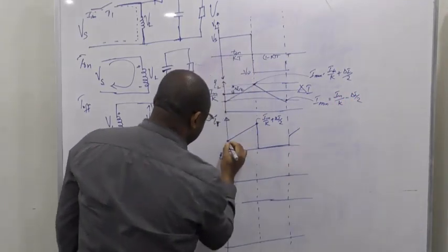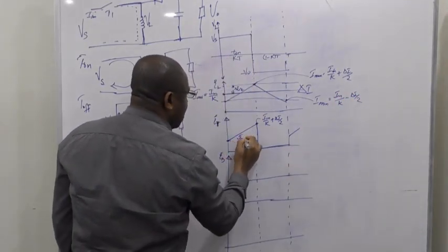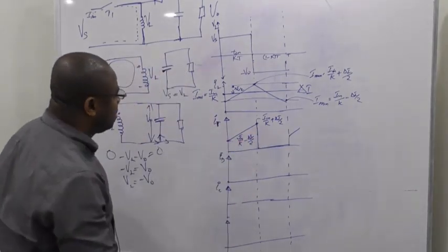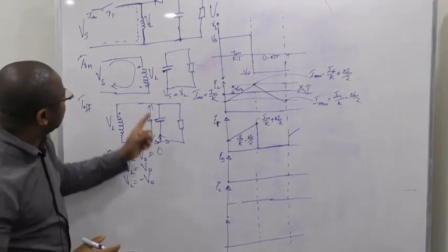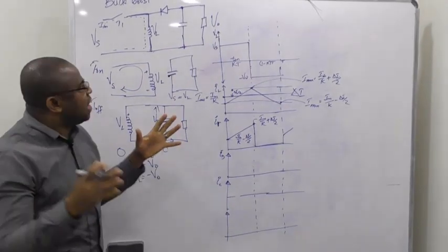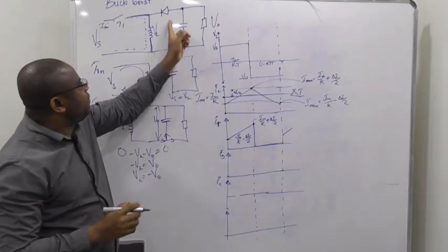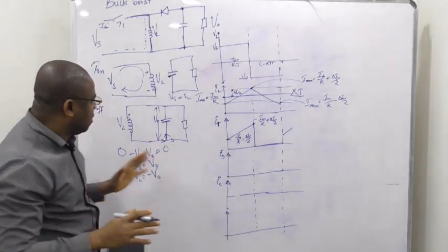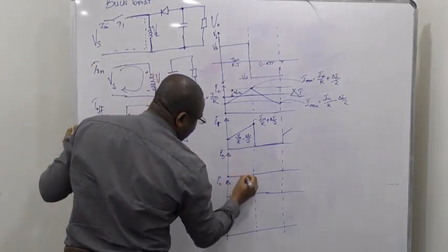The same thing here. Okay, here is I in over K minus delta I over 2. All right? Now let's look at what happens to the current through the diode here. Remember, at time of on, there is nothing flowing through the diode, so you get 0.